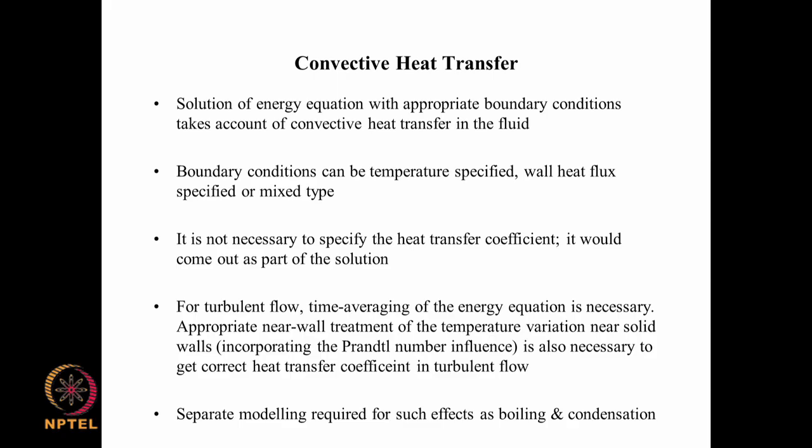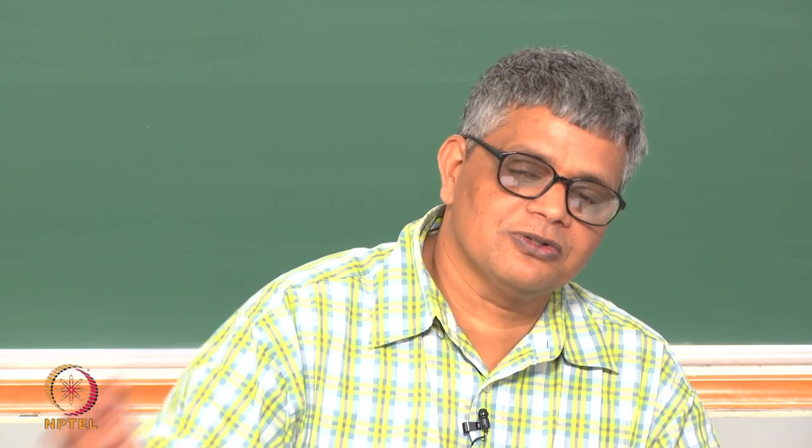We need to specify the heat transfer coefficient because outside the flow domain we do not know what the temperature variation is. We are not computing that. If you were to include part of the outside domain also in the computational domain, then you wouldn't have to even specify that, but that's a different story. So let's not go too much into that at this stage.